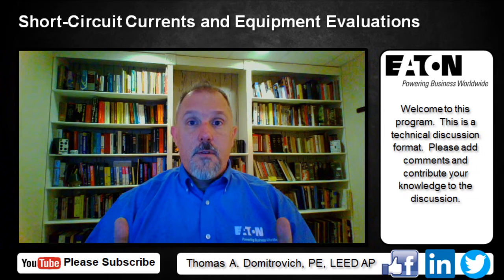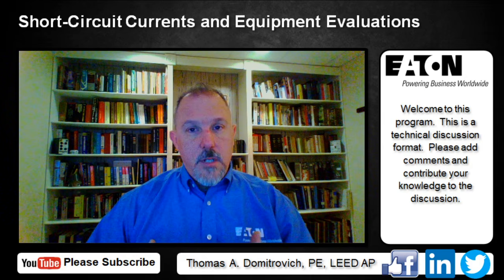Now, on the circuit breaker side, you'll have one breaker that will have different interrupting ratings dependent upon the voltage rating of the circuit breaker. So I can have a molded case circuit breaker with a high interrupting rating, 65,000 amps at 240 volts, but it could have 35,000 amps at 480 volts. You've got to really read the instructions and understand the labeling of the circuit breaker.